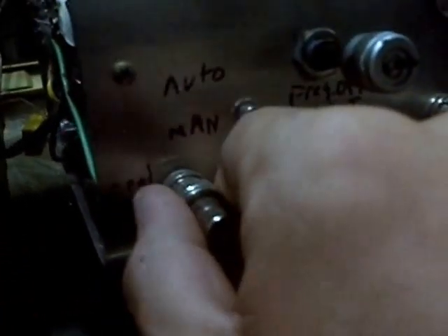And here let's show you the frequency generator I got. Basically I get the frequency range switch, a 4-way switch. Here I have another switch that I use for the capacitor. I can change the capacitance of the PLL to get other ranges for the frequency. Here is the output from the feedback signal, from the signal going into pin 14 of the PLL. I hope you can see the feedback signal there.